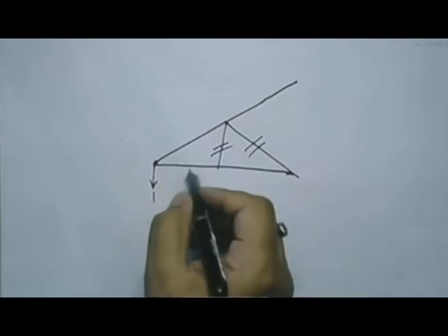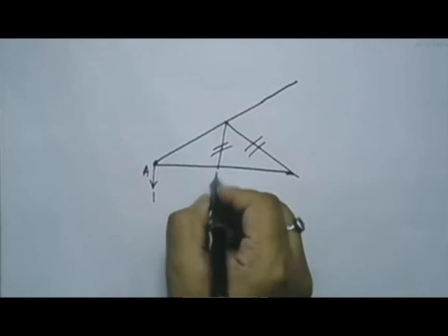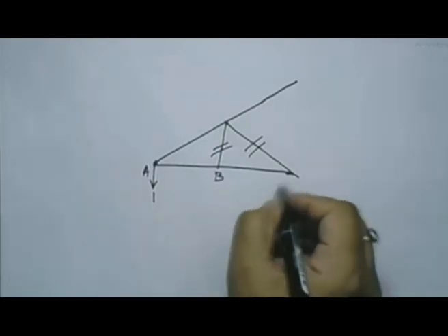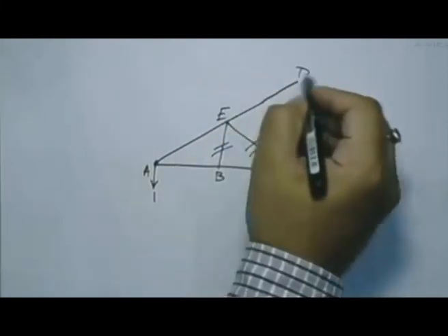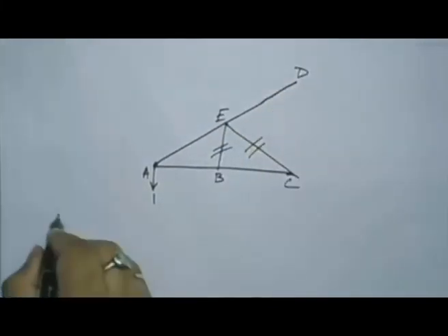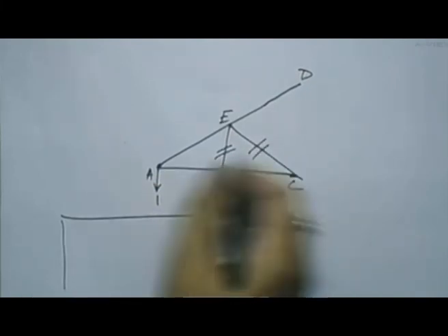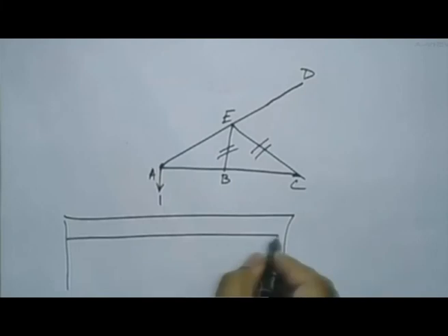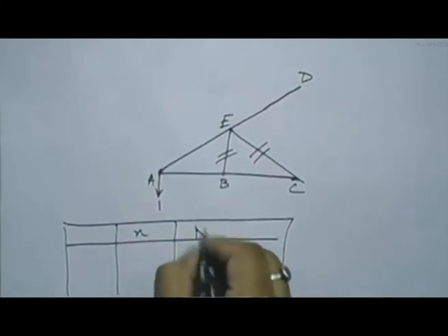So you get member forces in AB, BC, AE and AD. When you draw the table, you can straight away eliminate these two members, because under virtual load they will have no member force. So in other words, small n would be 0.